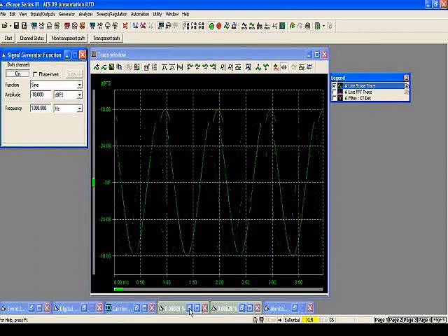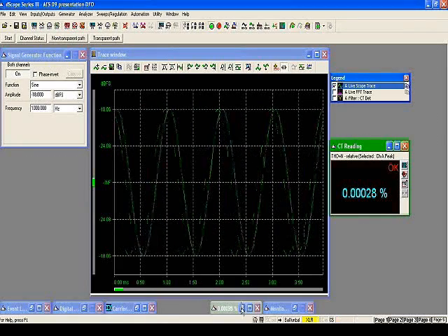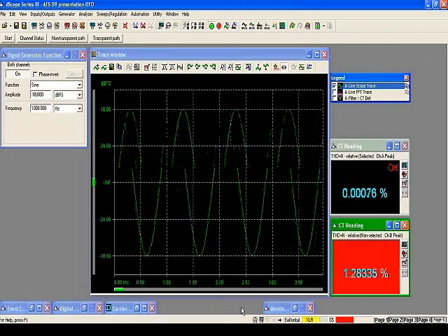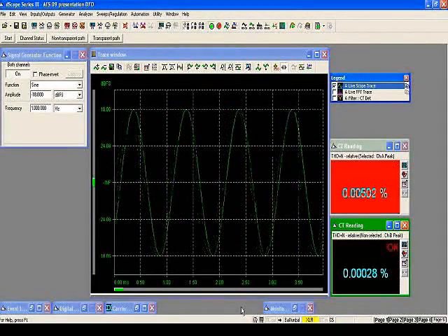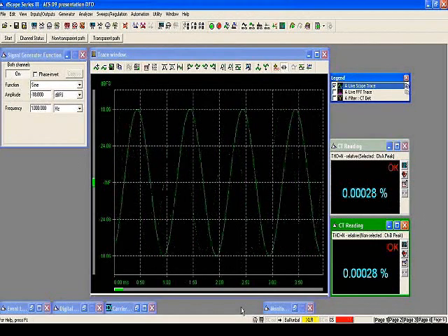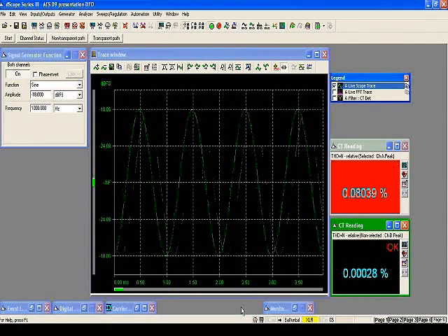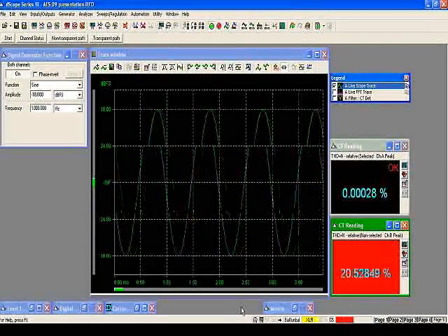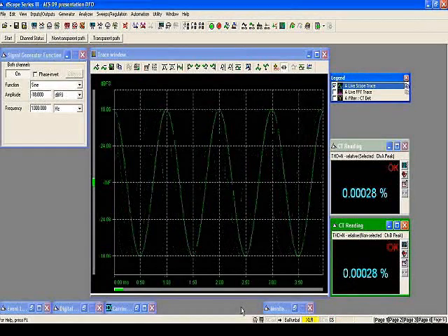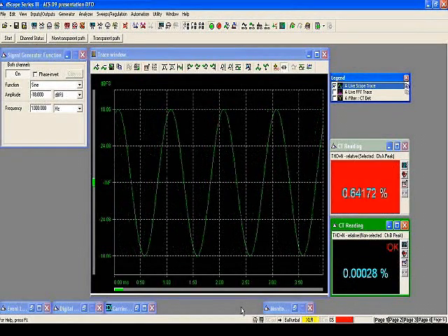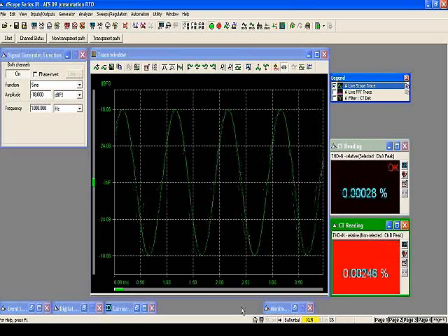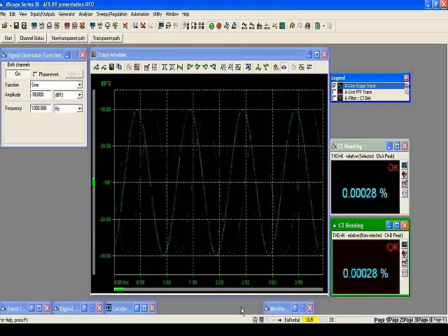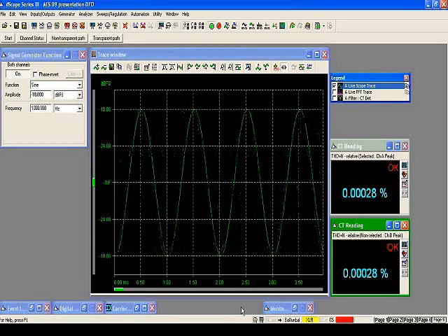However, what I'm going to pull up now is our distortion analyzer. And you can see we have some red alarms that are flashing when it's making the distortion measurements. And what we've set up is some very tight limits on the distortion measurements such that we can catch anything that's gone wrong inside that signal that we may not be able to hear or see. But that in itself, I mean, that's one tool. Tells us there's something wrong, but that in itself is not complete.